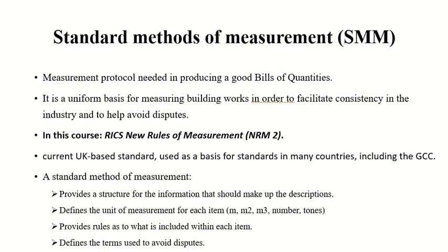And this will make sure that you don't have any conflicts later on. Nobody can claim, I wrote concrete quantity in square meters because I knew the depth is only 150 millimeters. Nobody can say this. Even if the depth was 150 millimeters, you should have calculated cubic meters. This is a standard. Got it? So later on there will be no fighting, no conflicts based upon that.